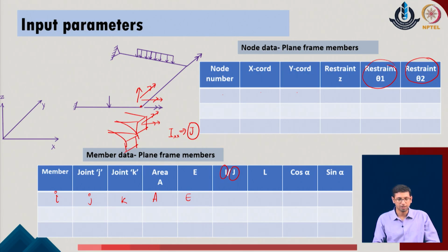So due to this bending component on the given system, we describe the second moment of area about this axis yy itself. So we look for either Iyy or Ixx in the given problem, which are the second moment of area required for the flexural and the twisting cases. Length of the member, cosine alpha and the sine alpha of the given system can also be defined once your coordinates in the given xy plane are known to us.